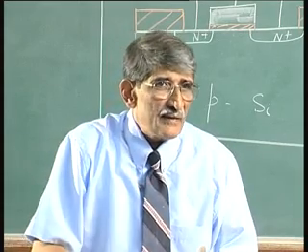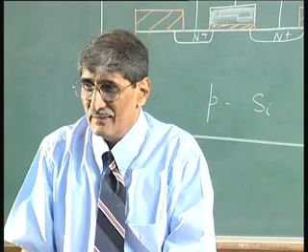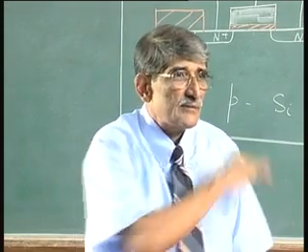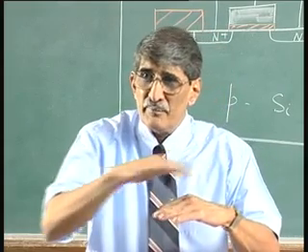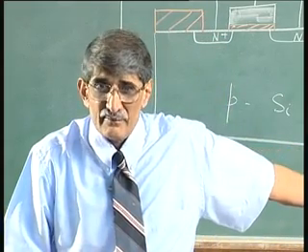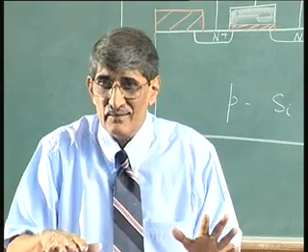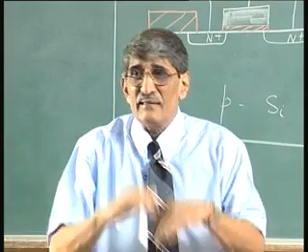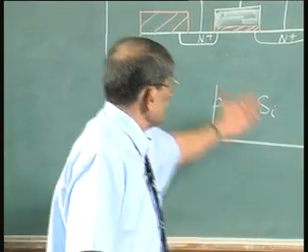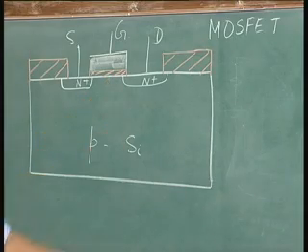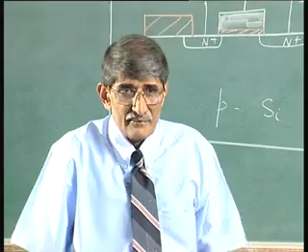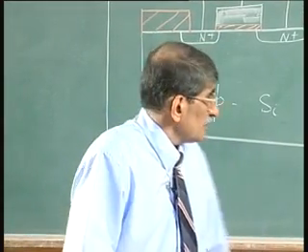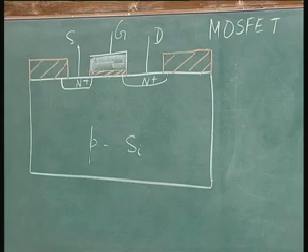To put it in a very simple way, any loss of periodicity gives rise to a level. If you add impurities, that is loss of periodicity, it gives rise to a level. You go to the surface, loss of periodicity, that gives rise to those levels, multiple levels, because it is a 2-dimensional affair on the surface. Okay. Now, you oxidize that surface with the good native oxide. You do that, those dangling bonds are saturated with this oxygen, silicon-oxygen bond. Okay. Immediately, you do not have the dangling bonds. Then what happened is, you remove those levels which I showed you, minimize them.